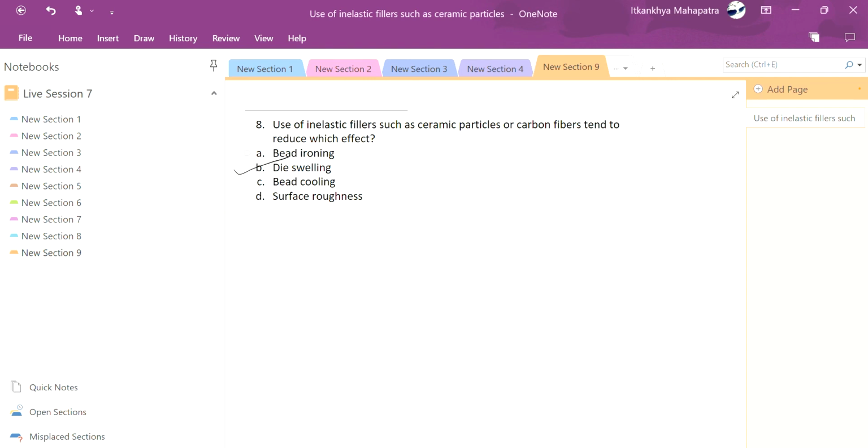This is the general characteristic, given by the Newtonian behavior. As you must be remembering, we have shear stress and shear rate, where we have the dilatant, Newtonian, pseudoplastic, Bingham plastic behaviors. Those were the various behaviors of a fluid. So for the FDM process, we follow the shear thinning behavior.